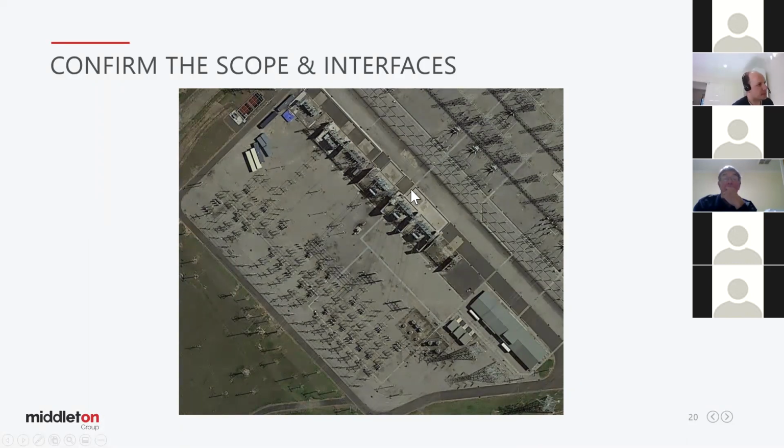And straight away from this nice Google Earth shot here, we can see that there are existing cable trenches which run over here to the building on that side. And there's also one on this side up here. That's actually going to the other control room. So there is a path. We just need to confirm if it's actually full, if it's in good condition, or if we need to actually install something new. And that might be an extension, or it might be okay. That's really confirmed during the site visit and based on an estimate of the number of cables that we will need to install.